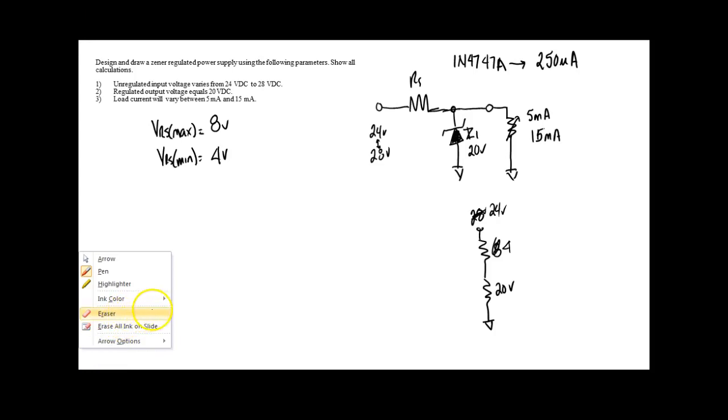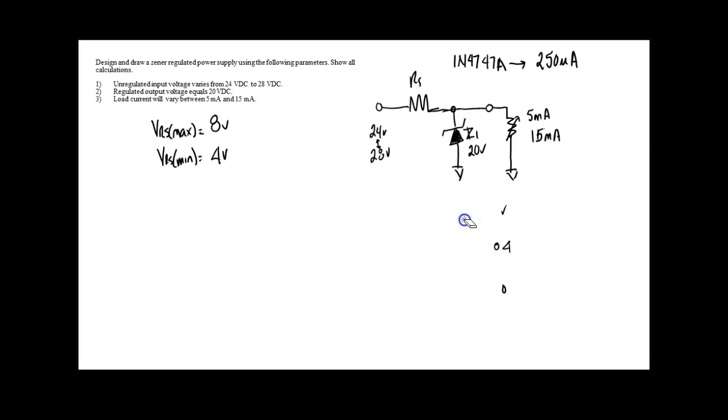Okay, so I know the voltage that resistor is going to have to drop. What we're going to do now is calculate what resistor would drop the minimum voltage at the maximum current, because everything after that would take care of itself. If the voltage goes up, the resistor is going to drop more voltage and it's going to move away from the knee, right? You understand? So what's the formula? I'm going to put the values in while we're doing it.